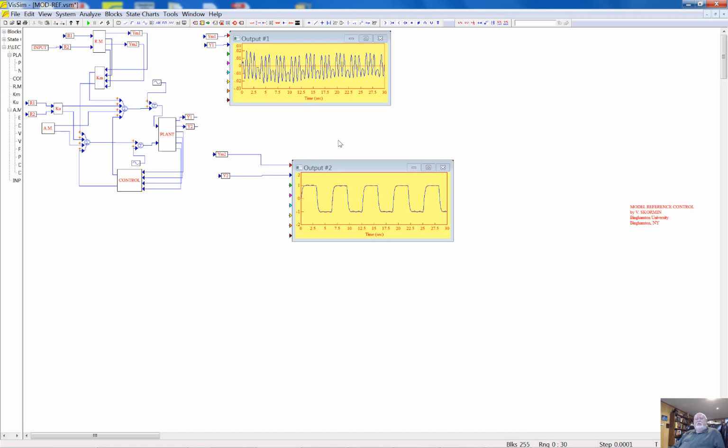The second approach, if you would recall solving the Lyapunov equation, the right-hand side of the Lyapunov equation is supposed to be a positive definite matrix Q with minus sign. I used unity. Nobody would stop me from using different definitions for matrix Q, and I probably would achieve further improvement of the adaptation results.